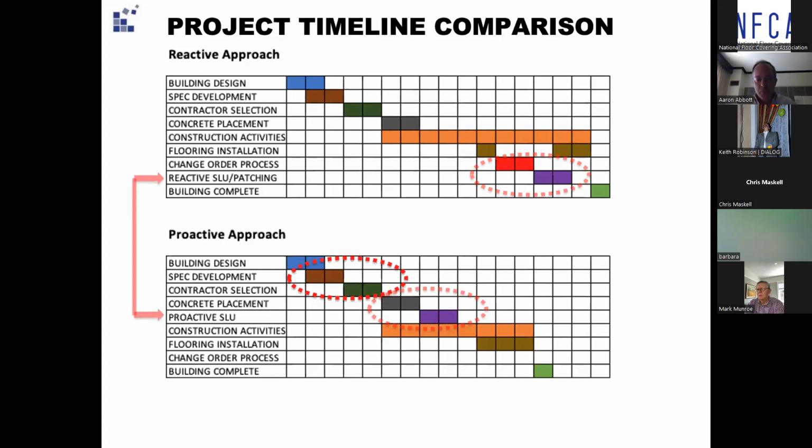to decide that, well, we're going to maybe let the concrete placement contractors make their structural slabs and not worry so much about floor flatness, and let perhaps another contractor, or the same contractor, it doesn't necessarily have to be a different one, allow for proactive installation of self-leveling, which is one way to solve or alleviate this problem.